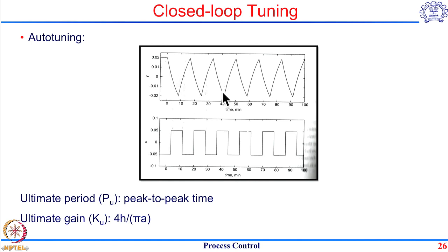It is not entirely an oscillation like you would see for a typical auto tuning method which you had seen earlier using a proportional controller, but this type of response also gives you some relationship between the magnitude of input change to the magnitude of output change, which will give you the gain.